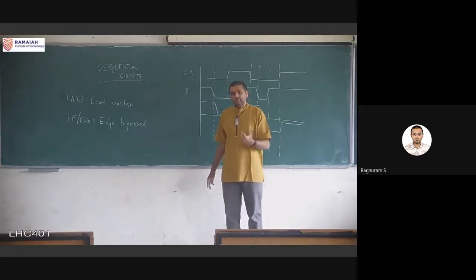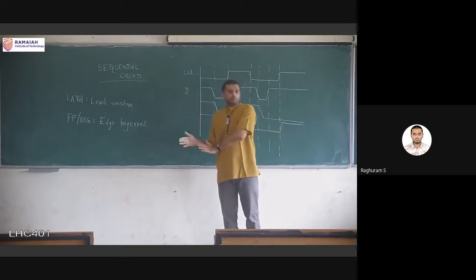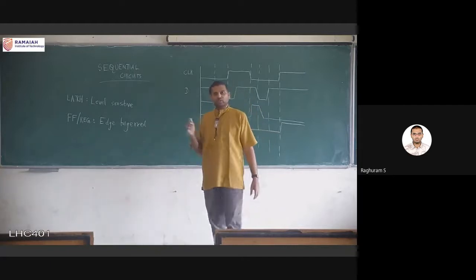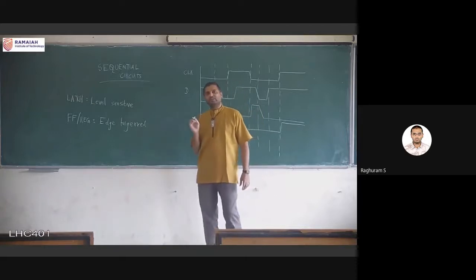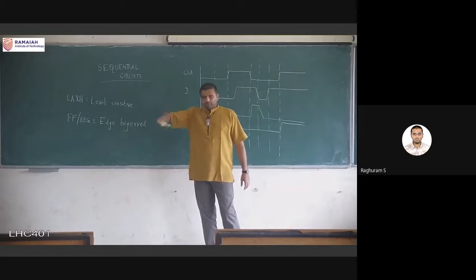That is, the data will be continuously passing from the input to the output. The flip flop or register, register always means flip flop, and it always means that it is edge triggered. It can be positive edge triggered or negative edge triggered.